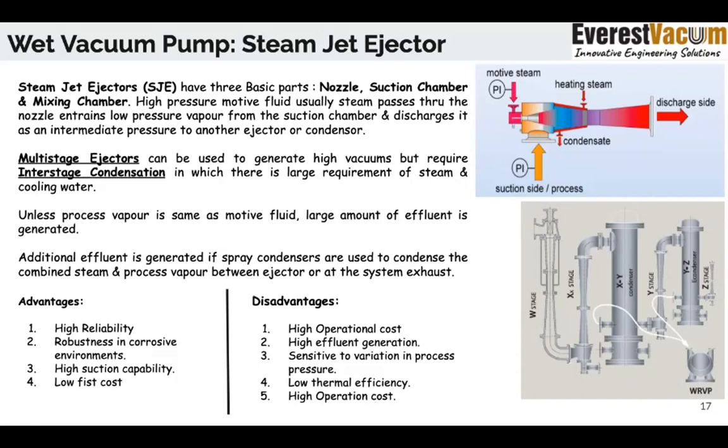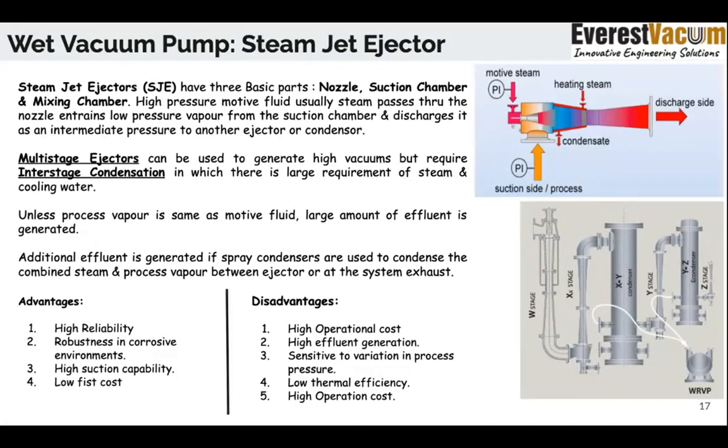But as soon as I start talking about acids, it creates a problem, because when steam mixes with, say, hydrochloric acid or some nitric acid, it creates an aqueous hydrochloric acid solution, which is 3 to 4 times more corrosive than concentrated hydrochloric acid itself. So in that case, we need to start going in for special exotic metals.